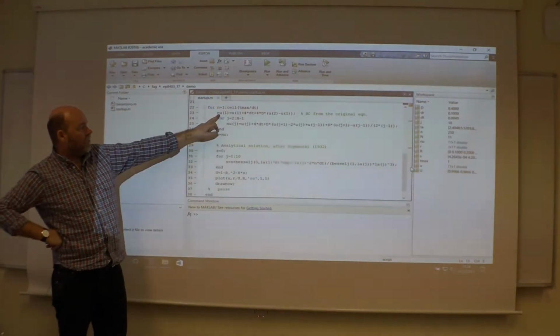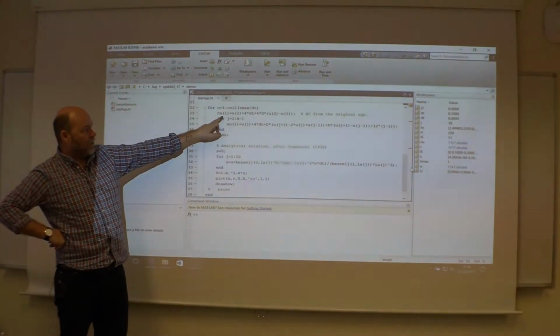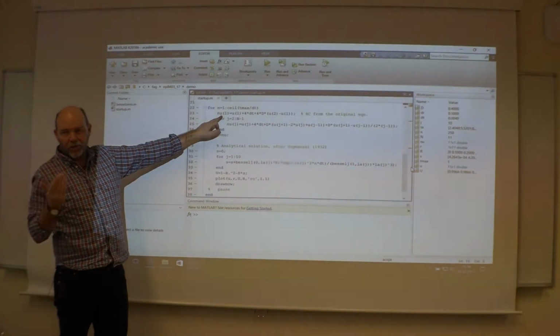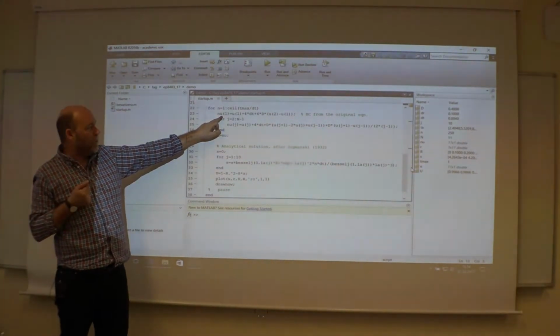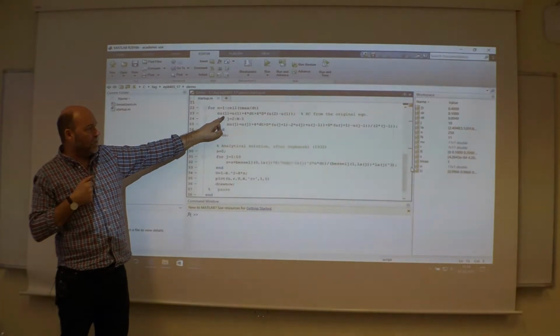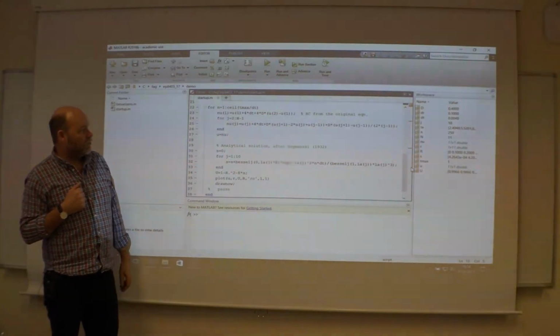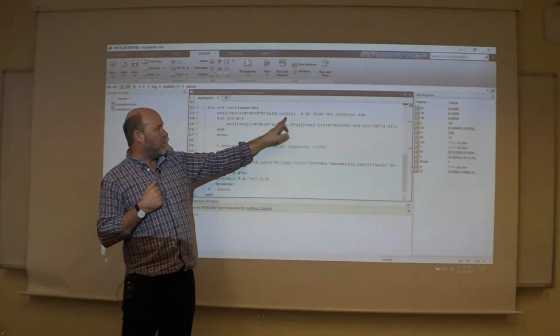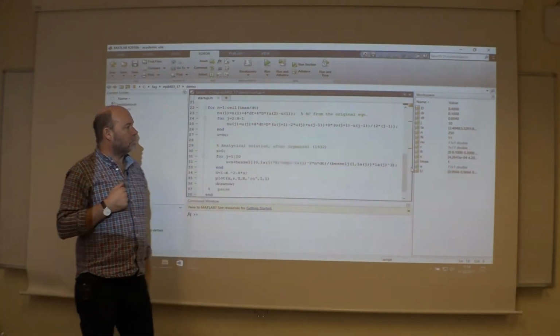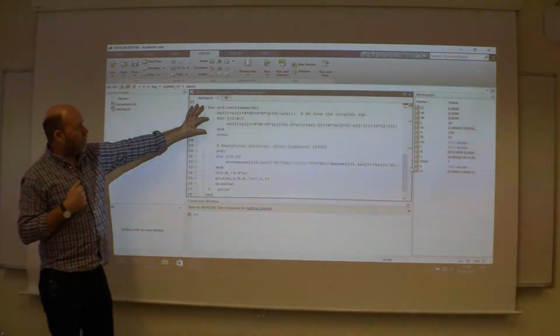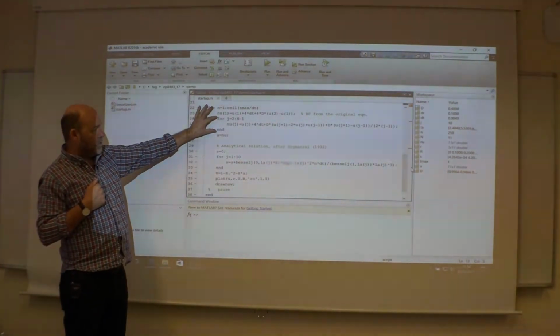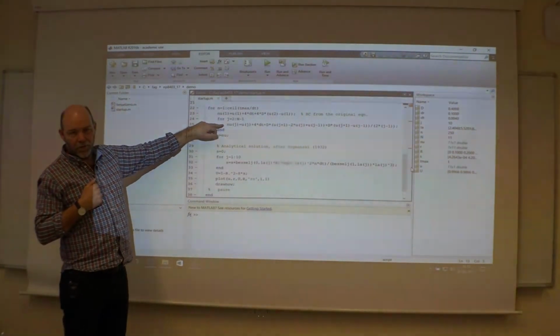Okay, I have to create the first one there. That is the boundary condition in the center of the pipe. So this one I have to sort of calculate specially. Derivative equal to 0, using the first and the second point. For the internal points, we will have this FTCS scheme for all of them.